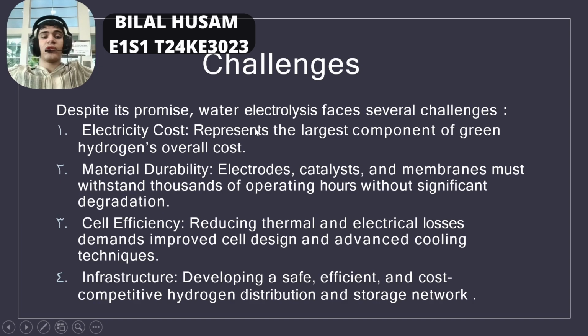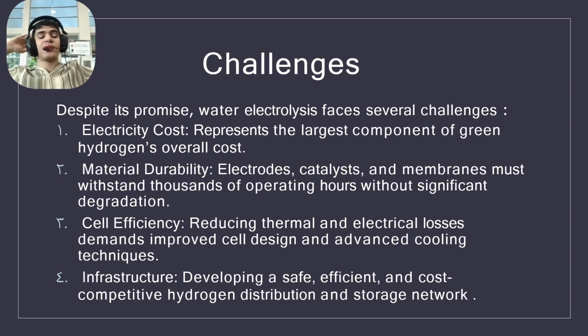Despite its promise, water electrolysis faces several challenges. First, electricity cost represents the largest component of green hydrogen's overall cost. Second, material durability: electrolytes, catalysts, and membranes must withstand thousands of operating hours without significant degradation.